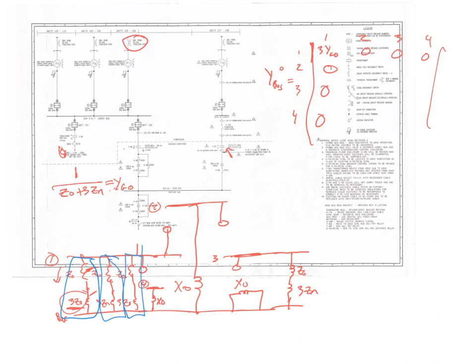Yeah, so I'm still confused with the Z naught and the 3Zn. I only had one Z value. There's 2 of them, right? You've got the transformer. How do I get to? You have the generator has an impedance, doesn't it? X0. And you've put an impedance externally into the neutral, right? So you have 2 impedances that exist there. This is not a solidly grounded system. It's an impedance grounding system.